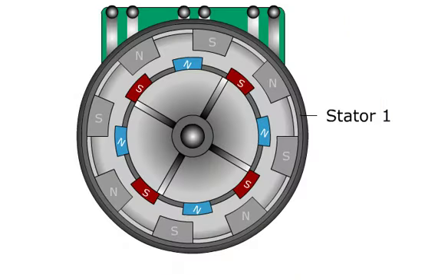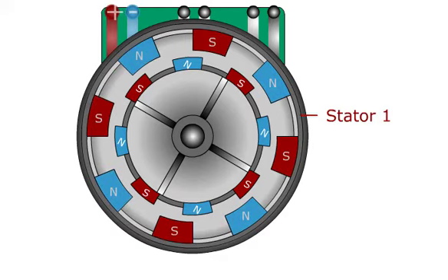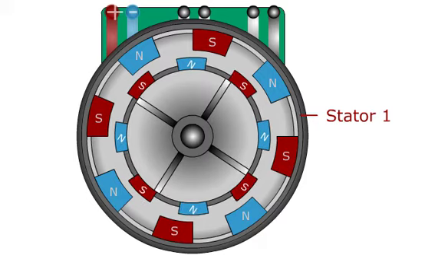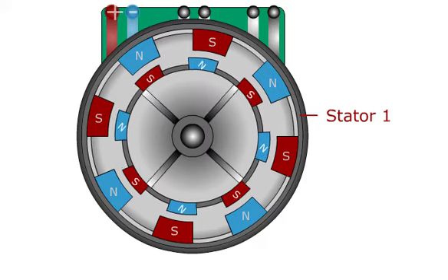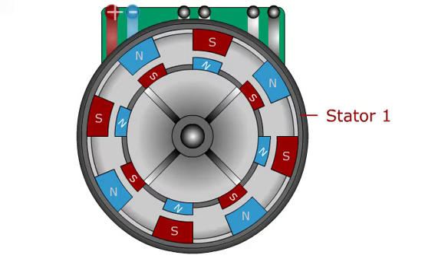If a part of the stator is magnetized through voltage application, the rotor rotates per the magnetic effect until magnetic stator and rotor poles with different names point to each other. Thus, this position of the rotor is achieved when the first part of the stator is energized and thus magnetized.